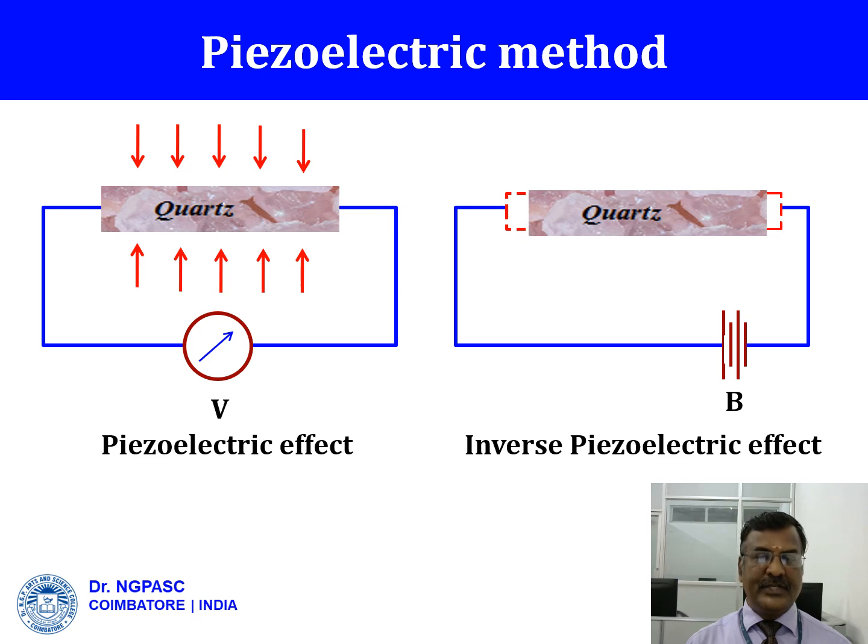of the crystal during one half of the cycle may increase, and during the other half of the cycle may decrease. When the AC electric field is applied continuously, the change in the dimension of the crystal also will take place continuously. So this is the concept of inverse piezoelectric effect. The inverse piezoelectric effect is used for the production of ultrasonic waves.